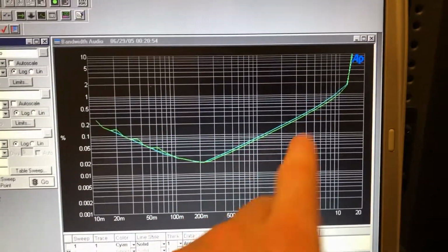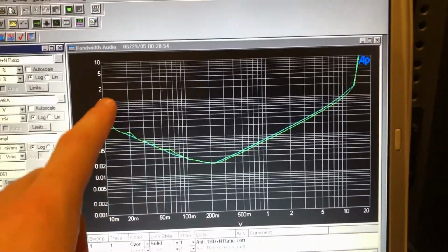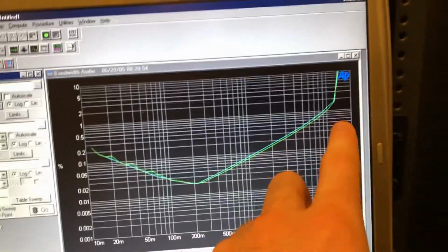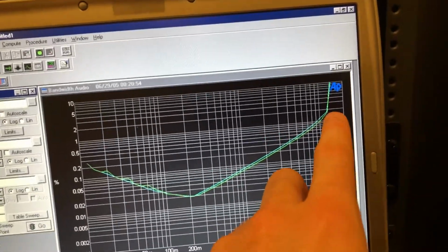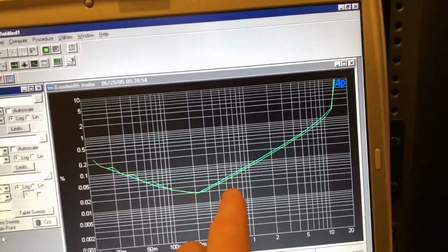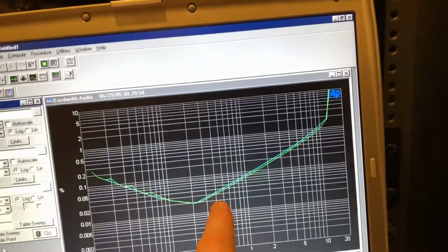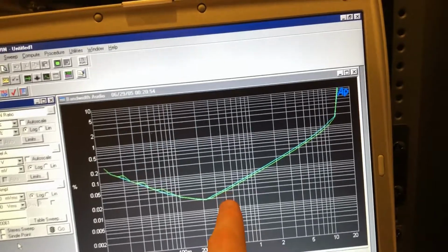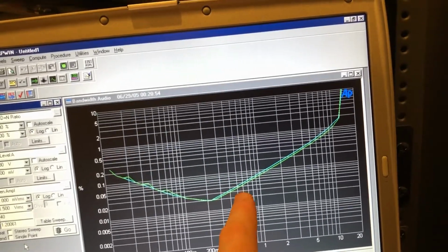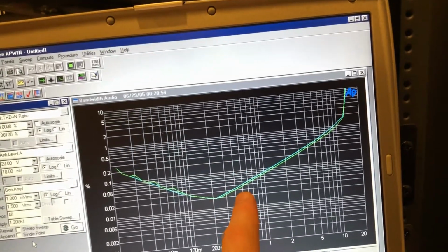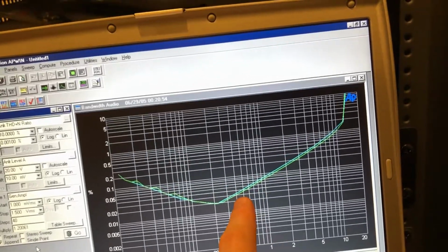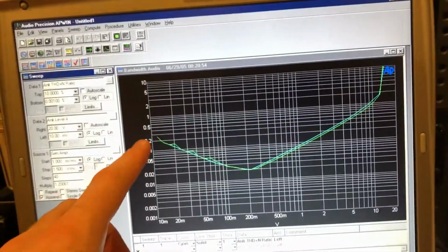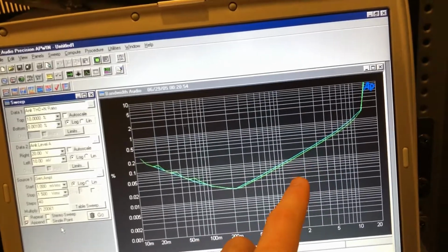And like I said, we shouldn't pay too much attention on these absolute THD numbers, because the other thing to keep in mind is we'll get some additional distortion cancellation once we add the driver, and even further distortion cancellation with the 845s, because the 845s, in conjunction with this gain stage, are going to provide some distortion cancellation, and we may see these numbers improve significantly.